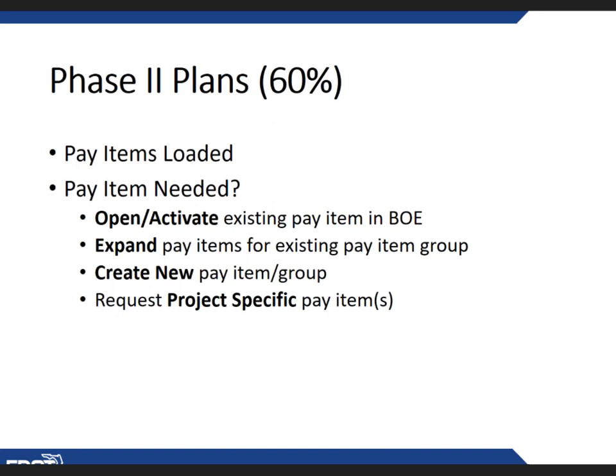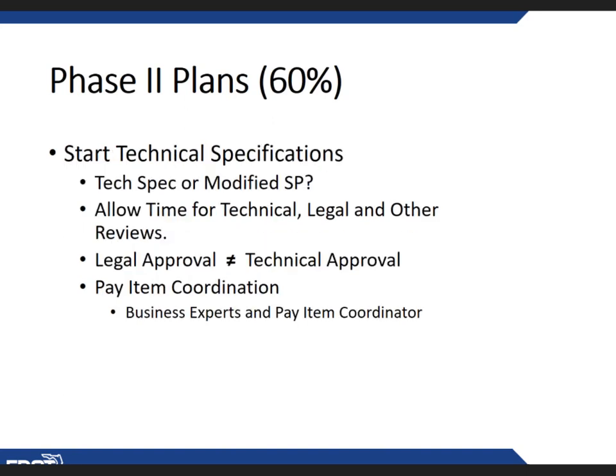I've seen a lot of things that were perfectly legal, but they open us as a department up for claims. I'll use the example of some items that may be measured per square yard. A designer may draw it in plan view, the square yards, just looking down, and that's fine when the slopes are very small.